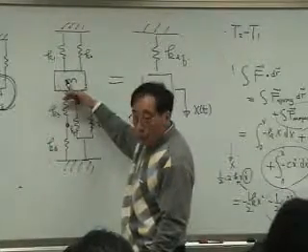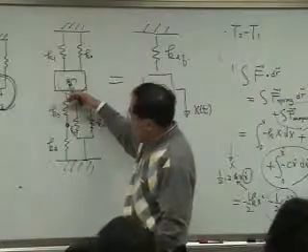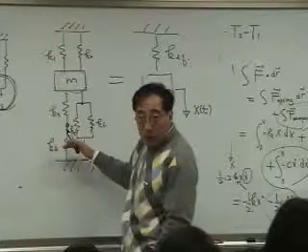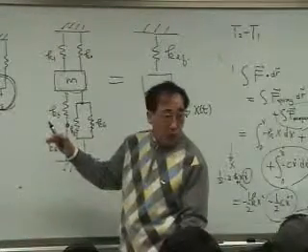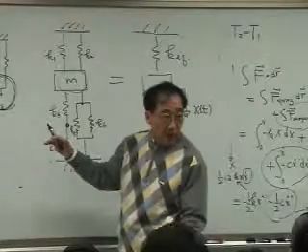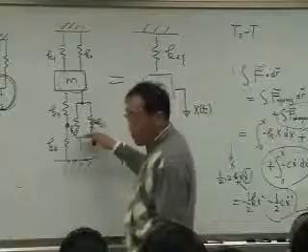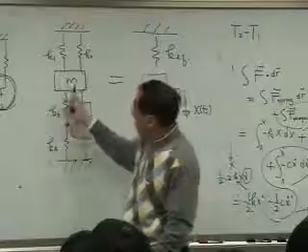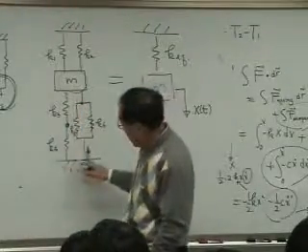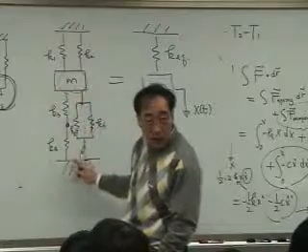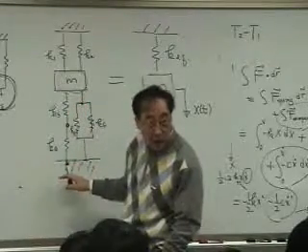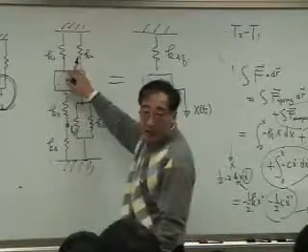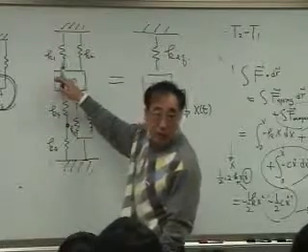If I have a unit displacement like this, then K3 and K4, what is conserved in K3 and K4? Force or displacement? Then I cut over here, and in the free body diagram, I will get the force acting on over here. And if I cut over here, I get the force acting on over here, the same as the force acting on over here. So force is constant in this case.